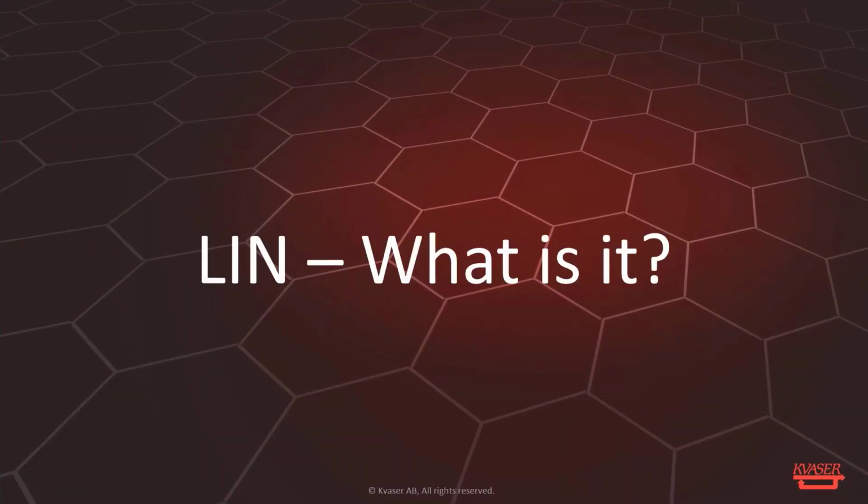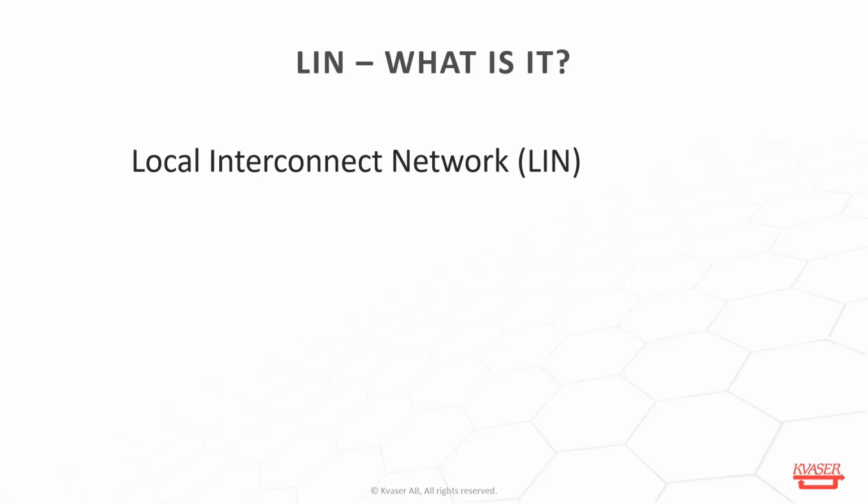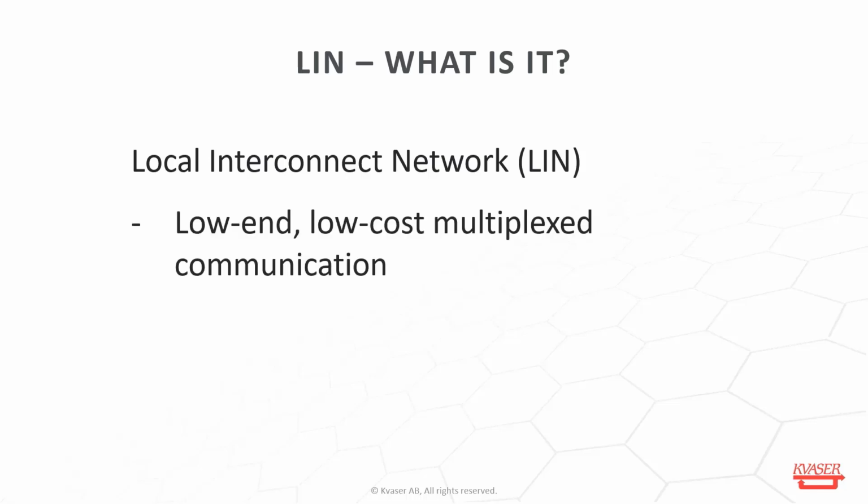LIN, what is it? LIN stands for Local Interconnect Network. LIN was created in the 1990s by a consortium of 5 auto manufacturers. The idea was to create something a little more cost efficient for controlling systems that didn't need too much data too quickly. If you didn't need to spend the money on something high speed, where possibly that was built in the protocol to begin with, LIN would be a good choice for you.